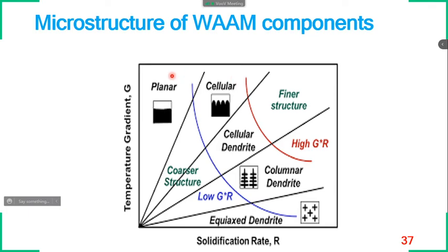Whereas in powder-based additive manufacturing, cellular grains may get formed, or cellular dendrites, or some equiaxed grains may get formed. But in wire arc additive manufacturing, it is very, very rare to see any cellular grains, due to the very high thermal gradient. As we deposit a subsequent layer, more thermal gradient will be stagnated. So due to the complex thermal history, we can expect only columnar dendrite or equiaxed grain morphology. So that is what we are making our point clear.